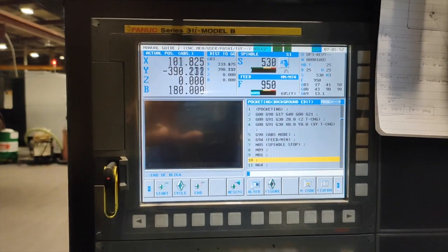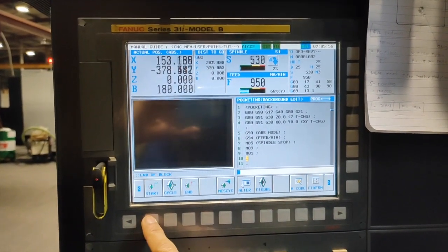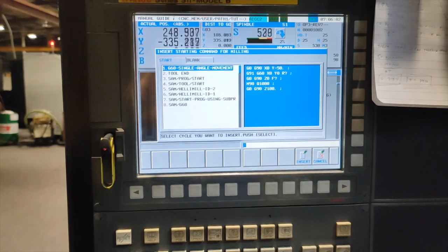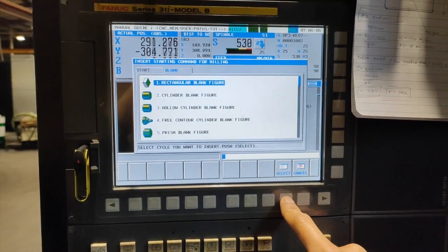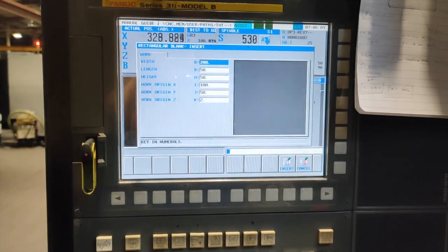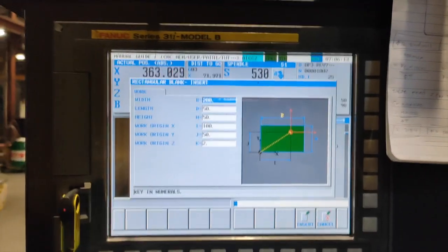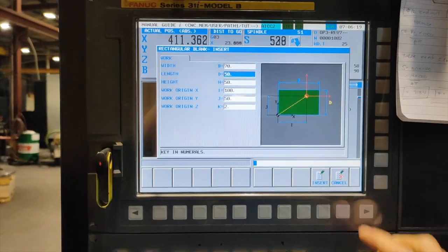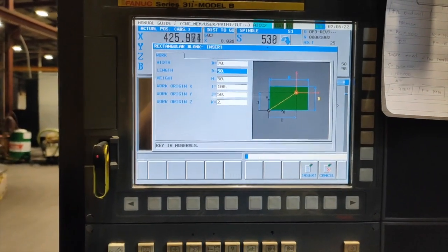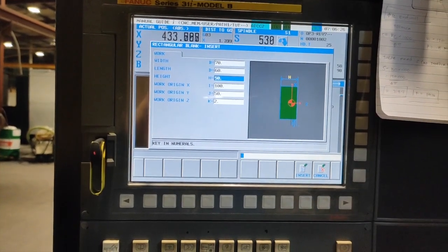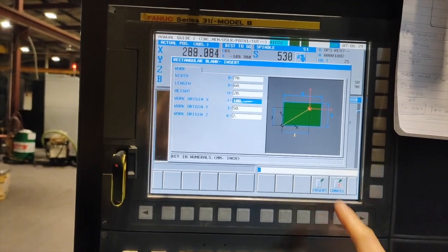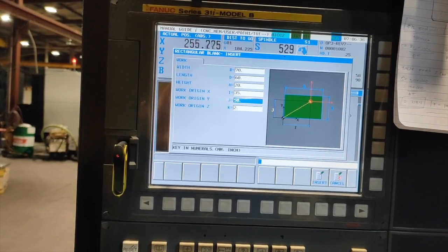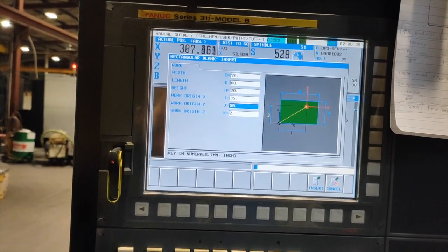And also guys, I forgot to put our blank, so to put a blank, go to start and select blank, select, and the size of our blank is, let's say the outside is 70, and the length D is 60, and the height is 20, and our datum is at the middle, so half of 70 is 35, and half of our 60 is 30.